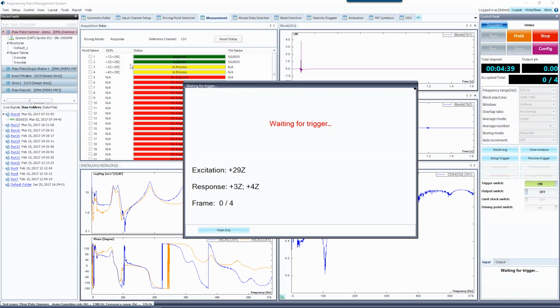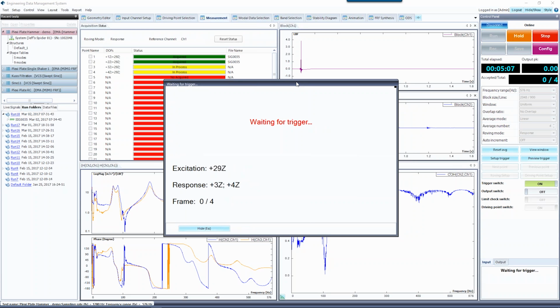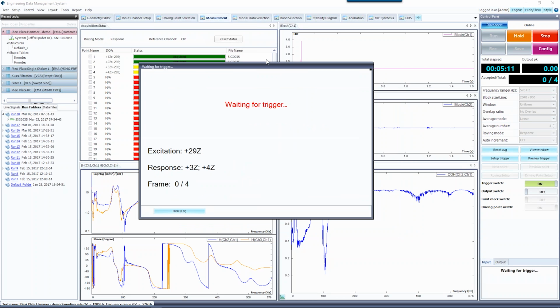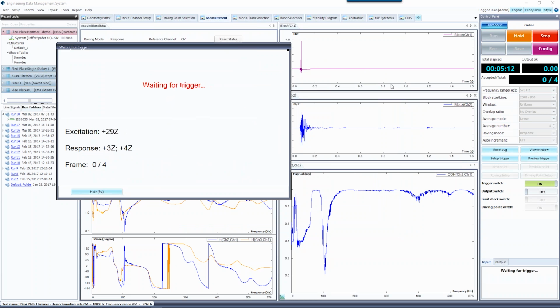And some people may use triaxial. For that case, for every point, you will have, say, 1Z, 1X, 1Y, depending on your setup. So you can use 3 channels as the triaxial: channels 2, 3, 4 are all measuring point 1. And then for the second one, you need a large channel count system, basically, if you're dealing with a large structure that has more points and you have more transducers. So you finish that, but you can do it in a triaxial way.